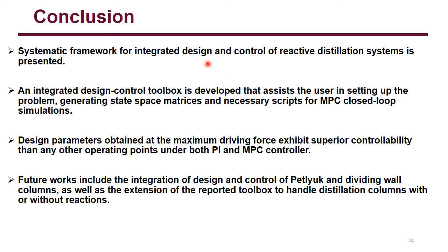In conclusion, we have provided a systematic framework for the integrated design and control of RD systems. We have also developed an integrated design and control toolbox that assists the user in setting up the problem, generating the matrices, and writing all the scripts for the MPC closed loop simulation.